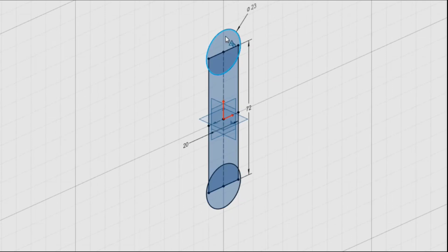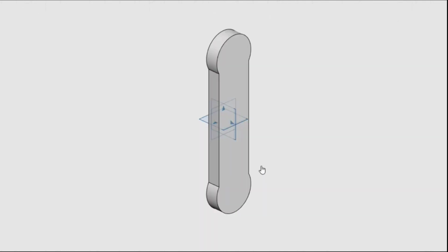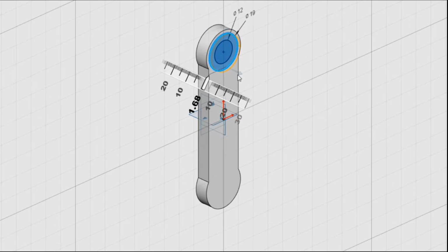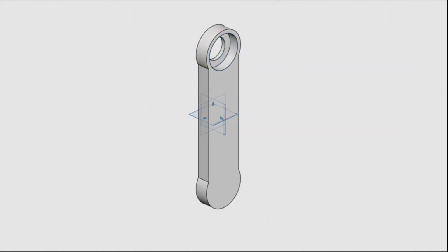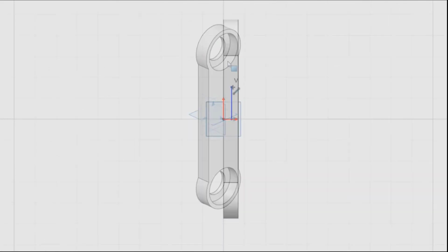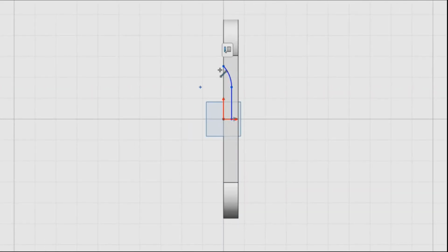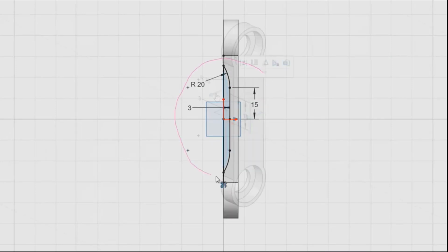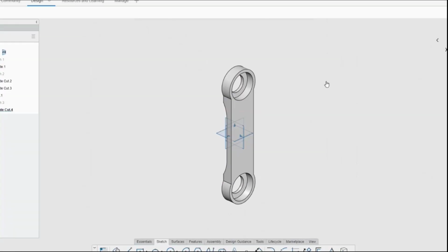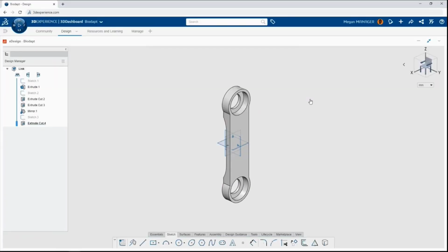When it comes to 3D instant, you can even select all the contours and drag them according to the requirement, and you can even create the holes and pins by using the same 3D instant tool to create the pockets and all. You can use the advanced tools like mirrors to mirror all the features. The advanced complex curvatures we have done using SolidWorks, here also we can do within a fraction of a second. All the shortcuts and superb modeling features are also available inside this particular XDesign.